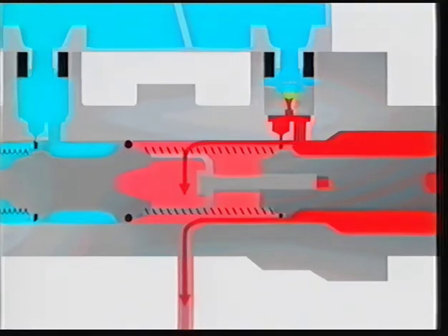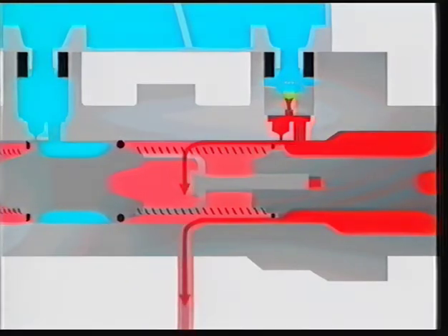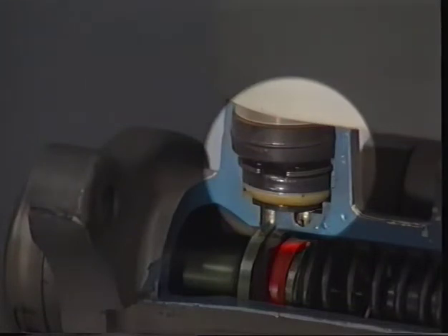This master cylinder features a stepped bore on the primary circuit to initially displace a large amount of fluid and therefore maintain pedal height. This extra displacement is controlled by the fast fill valve. The valve opens at a predetermined pressure and redirects the remaining fluid from the large bore into the reservoir.